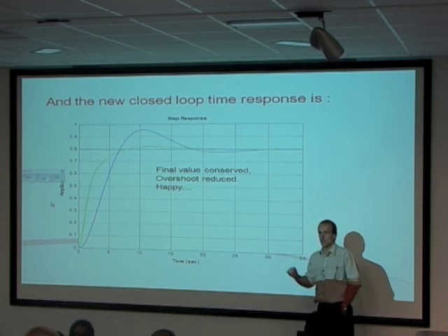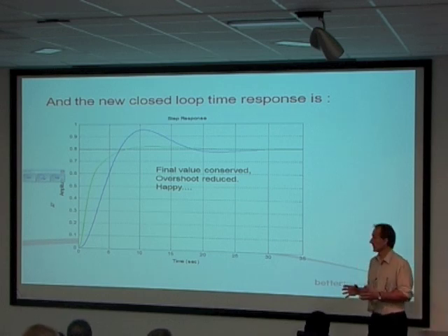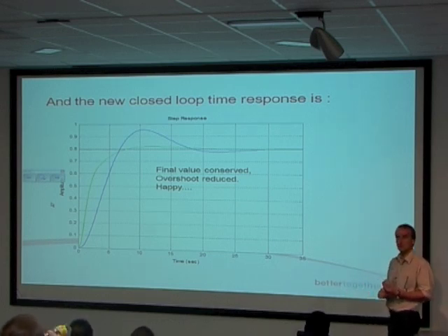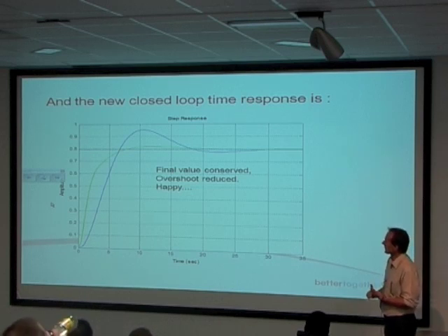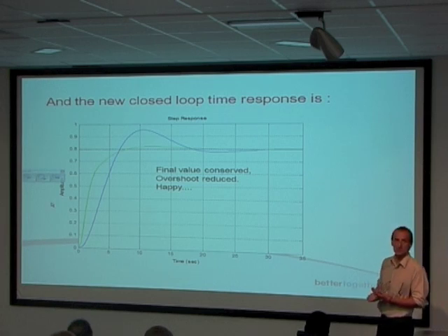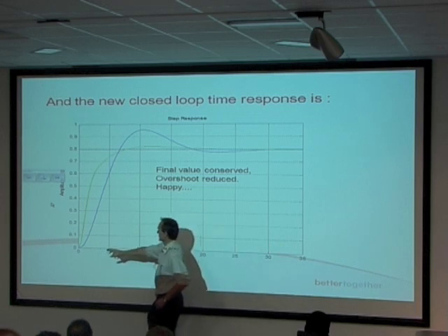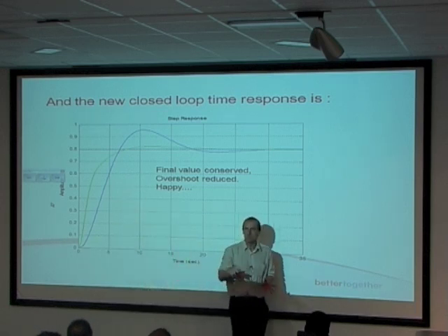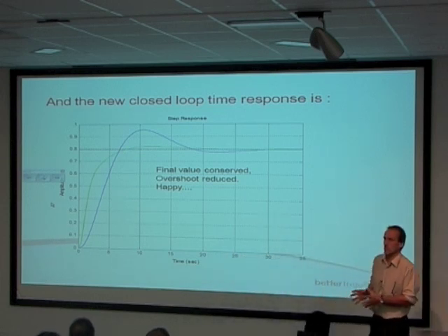So if you look at those responses and think of the terminology from when we're talking about time responses, thinking about things like rise time, settling time. The rise time, to be fair, isn't very much changed. Because the rise time really is about this first bit, isn't it? Between 0 here and 0.8. That's the bit where we're concerned with the rise time. So that definition, I haven't managed to change that very much.